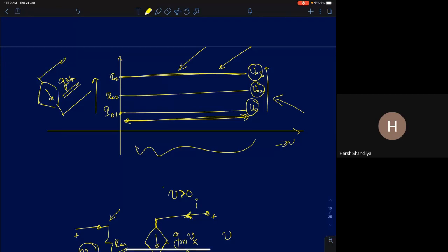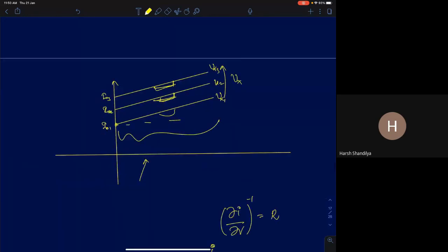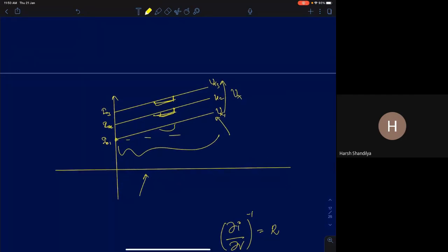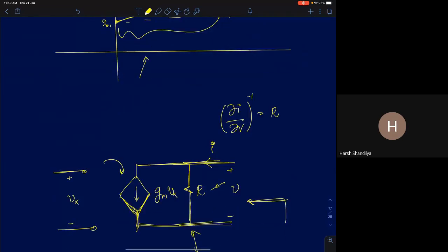Now what I'm doing, each current source I'm modeling it with a finite resistance. Okay, that's what I've drawn here. This same current source now has a slope. So previously for a single current source, when it had a slope, we modeled it with a current source and resistor in parallel. In the same way, for a transconductance amplifier, the transconductance VCCS model as well, if it has a finite slope, then with a slope given by 1/R in this example, I can model it as a transconductor and resistor in parallel. Same way as the previous example.